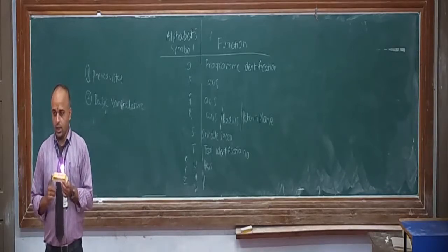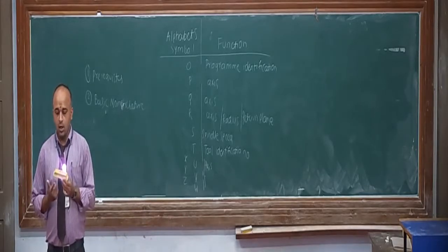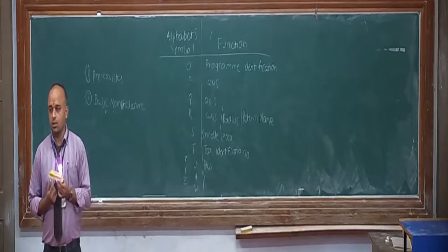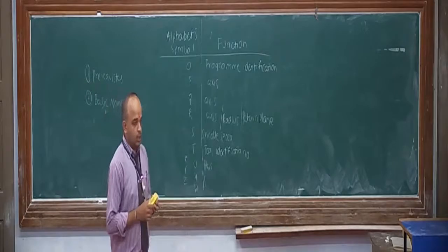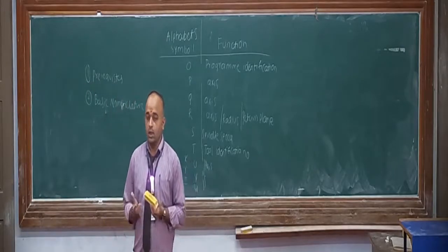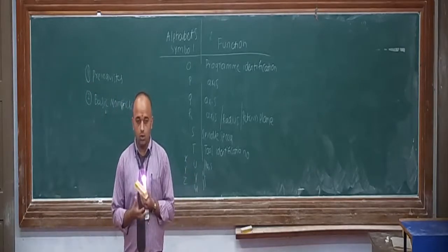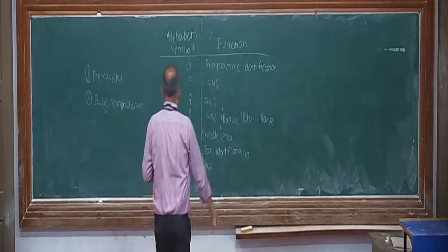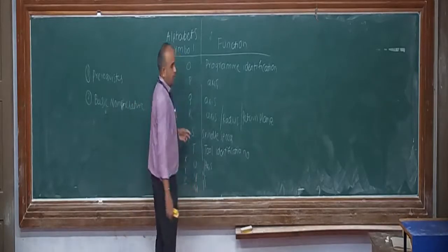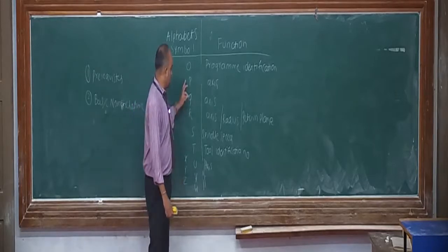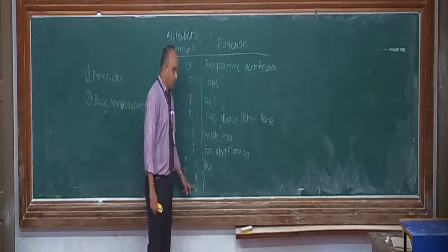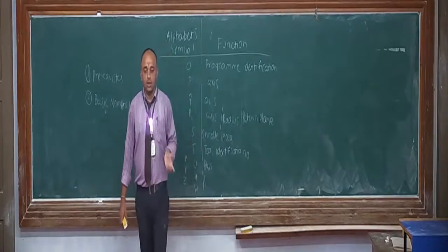For operation 10 I fix one axis, that is XYZ. Operation 20 I fix XYZ. But sometimes the programmer might get confused about which axis to utilize for what. So there is an option given. If the product is very complex, the operator has an option of using PQR or UVW rather than XYZ, so that confusion doesn't arise.